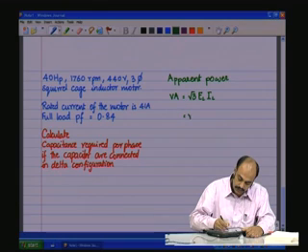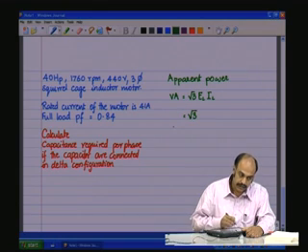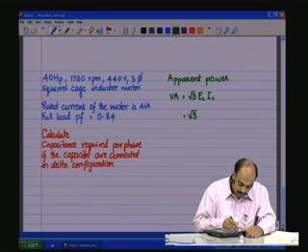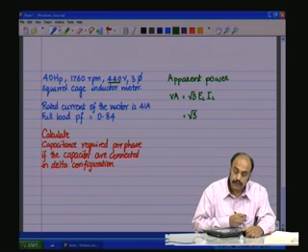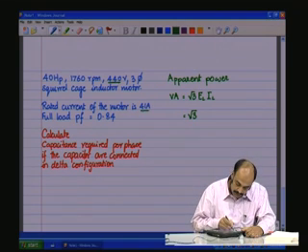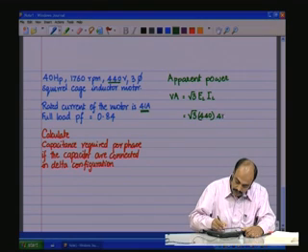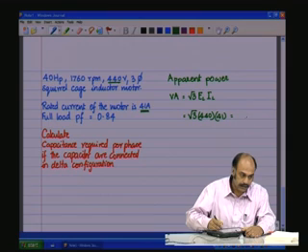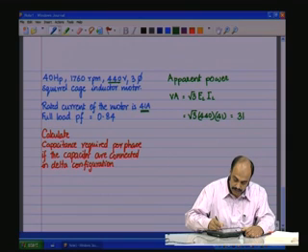So that is going to be root 3, the line voltage is 440 volts, and the line current is 41 amps. The value is given here. So 440 volts into 41 amps, and that is 31.2 kVA.